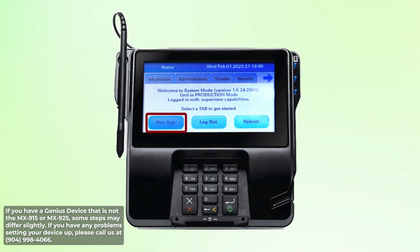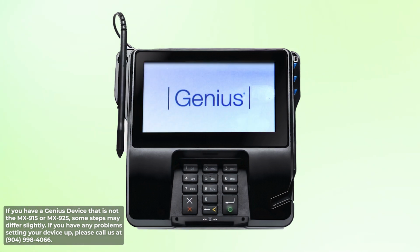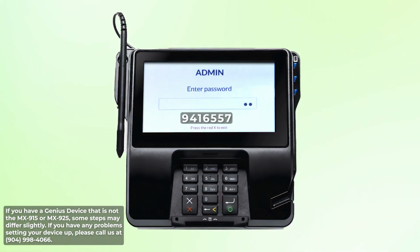Click Run App to begin the Genius application again. This may take a minute to complete. The Genius idle screen will display when completed. Press the 0 button 3 times on the Genius idle screen and key the password 9416557 on the admin screen.